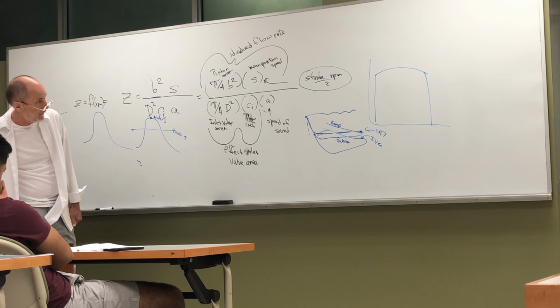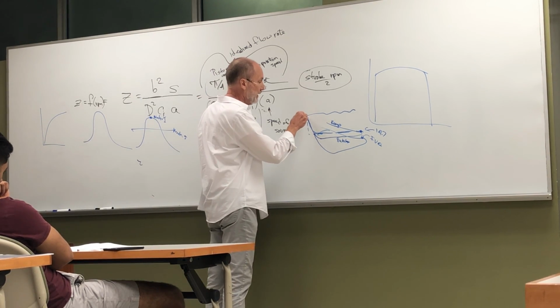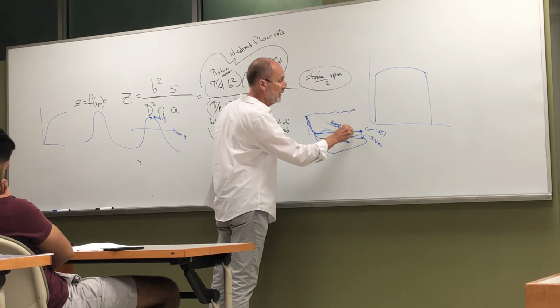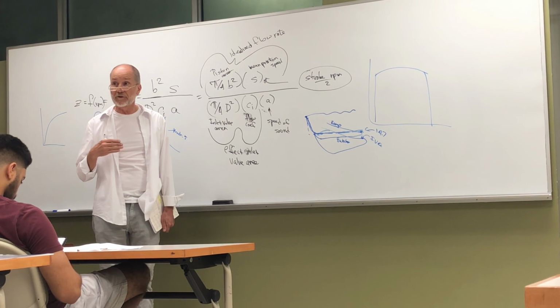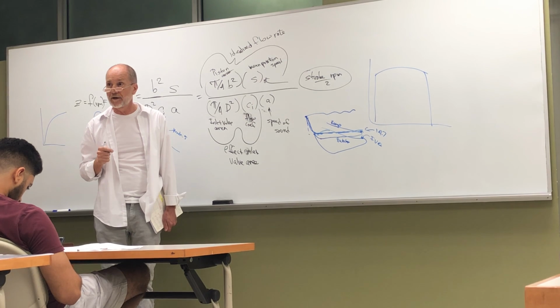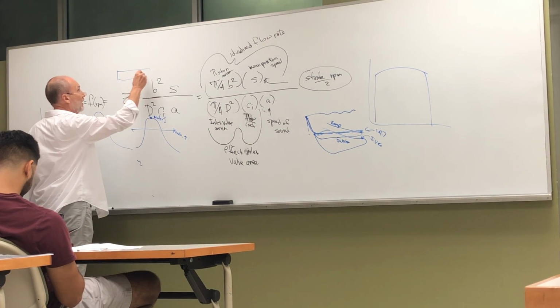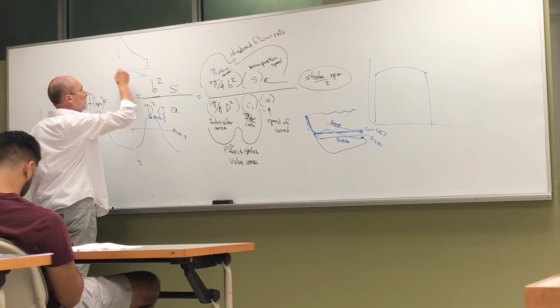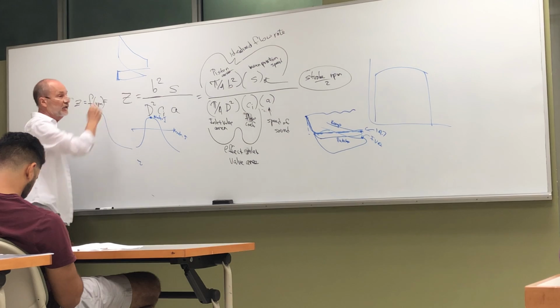Just to clarify, the picture you drew looks different from the picture. Is that at 0.2 Mach index? Mach index 0.2 is very near the rectangular pumping loop that we draw when we assume instantaneous valve opening and no resistance to flow, at full throttle. When we did our PV diagrams, the reason we had this straight line here is we assumed we can open the intake valve instantaneously and there's no resistance to flow. When there's no resistance to flow, you immediately go to the lower pressure.